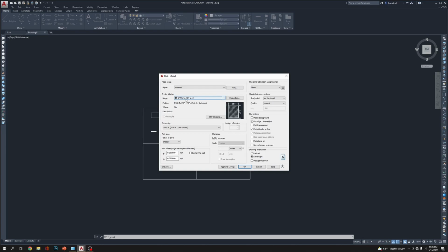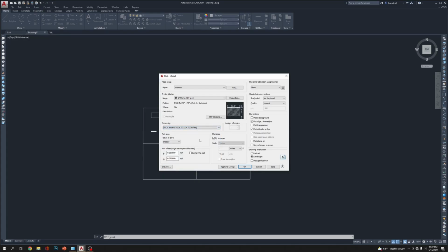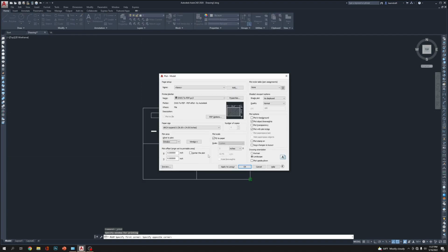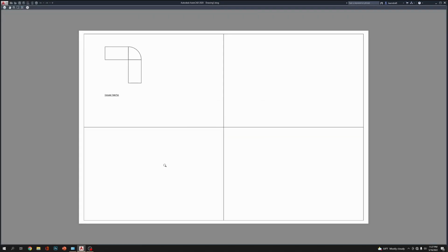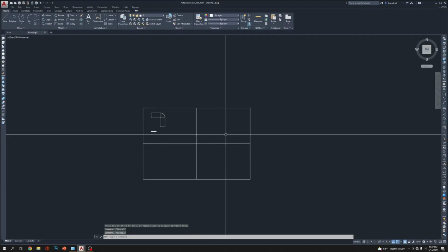This one is good, DWG to PDF PC3 is good. Then I'll go to expand D, architectural expand D 36 by 24, and then from display I'm going to go to window, click here, click there, make it centered, looks like it fits well, right? Look at the preview. Okay, looks very good. I'm going to press Escape, just an example.